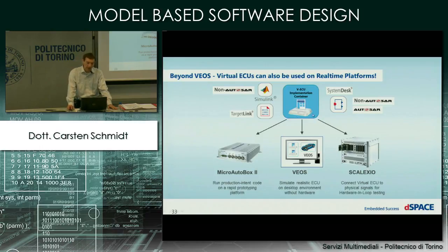So you can use this to add ECUs to a HIL simulation system where you don't have physical ECUs, so you take virtual ECUs. Nevertheless, you plug it into a system that does real-time simulation of at least one physical ECU. That is not virtual validation anymore, but additional use cases that are possible once you have these base techniques.